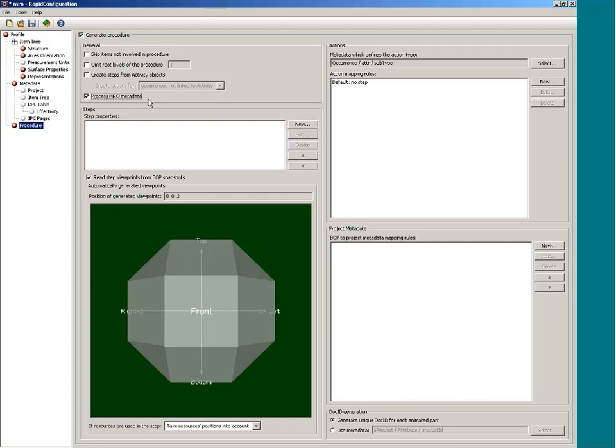Currently, the algorithm is not customizable, and it's possible to enable Service Planner import, and it will work because it is already set up. So now you can enable this checkbox, save the profile, and use it in Teamcenter Service Planner, and it will import all data you need. So this is it.